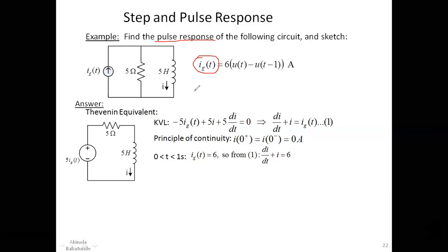So we could go back to the Thevenin circuit we talked about the other time. If you remember, we said that R Thevenin is always equal to R Norton. I also remember we said that when converting a Thevenin circuit to a Norton circuit, VT is equal to RN times IN.